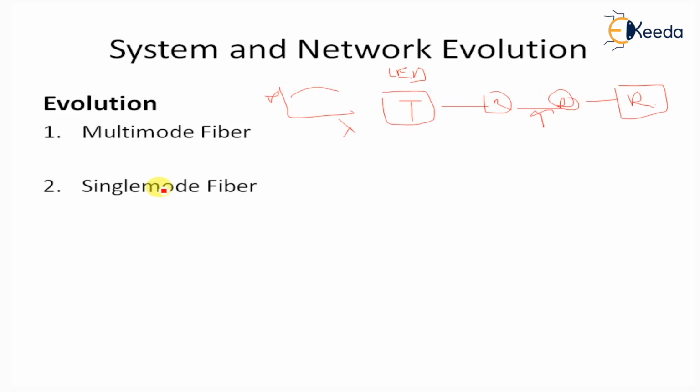Single mode fiber has a relatively small core diameter of about 8 to 10 microns, which is a small multiple of the operating wavelength range of the light signal. Using single mode fiber effectively eliminated intermodal dispersion and enabled a dramatic increase in the bit rate and the distance possible between regenerators. This system typically had a regenerator spacing of about 40 km and operated at a bit rate of a few hundred megabits per second.